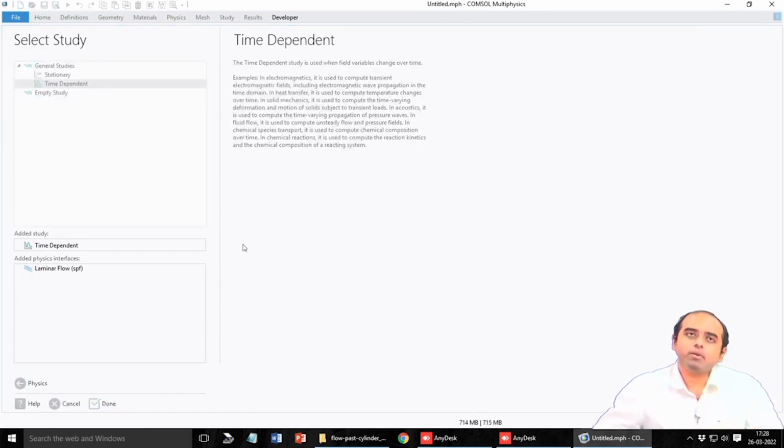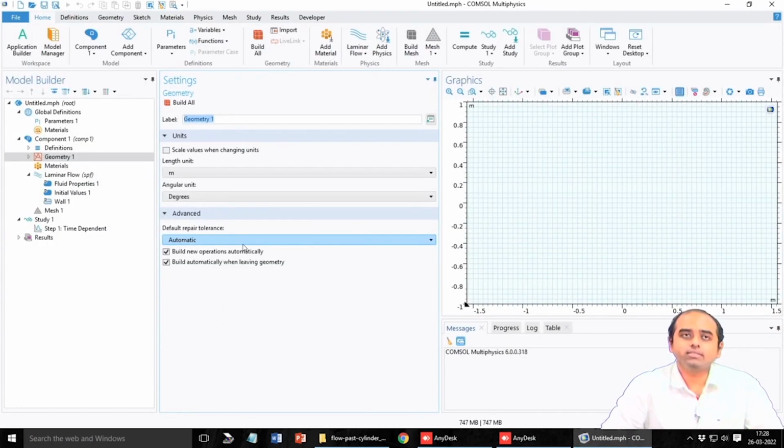Often time dependent problems are also helpful in studying scenarios where the steady state solution is very difficult to achieve or to find. Even though theoretically it is possible to have a steady state solution, or theoretically the equation satisfies the steady state condition, you can solve the transient condition and evolve the process towards a steady state. That is where the time dependent problem is useful.